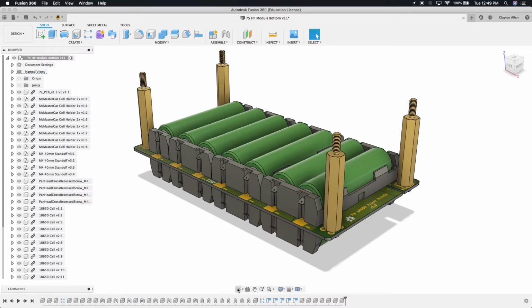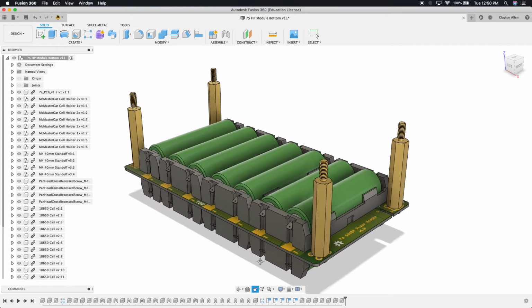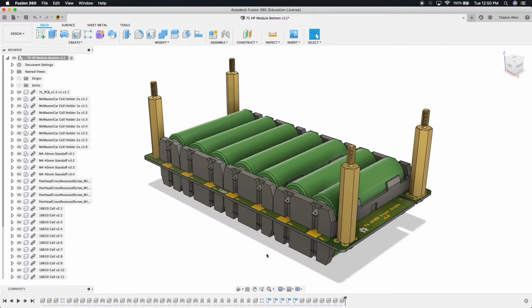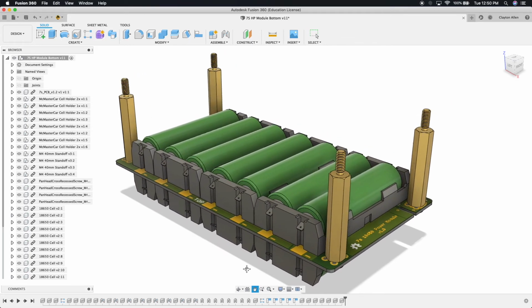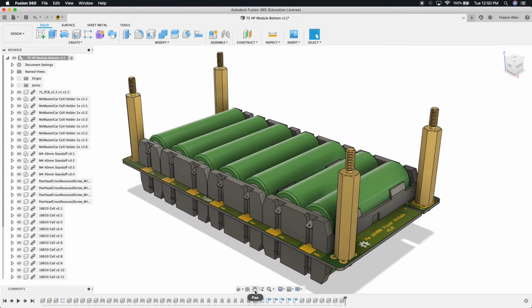Okay, now let's take a look at this menu item just down below. This is called the display controls. So we could do constrained orbits and free orbits. We can take a look at something. We can pan around, so I can click this and click the pan button. You can also do that by holding the center wheel on your mouse. If you click and hold that, you can pan around like so without having to use this.